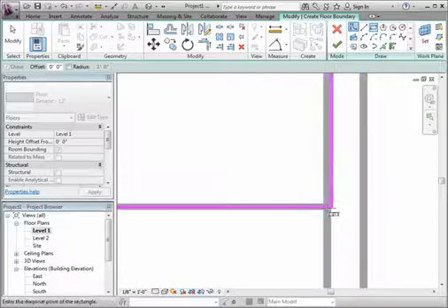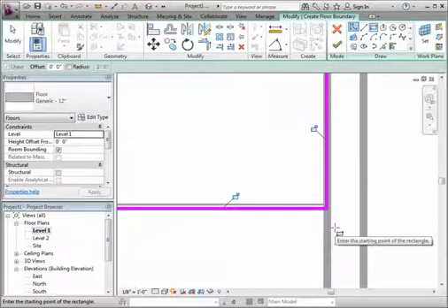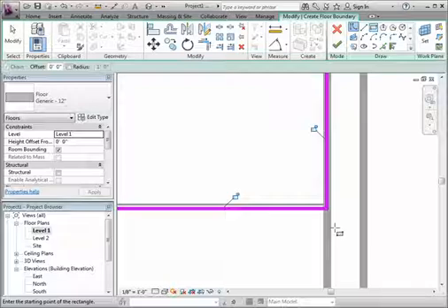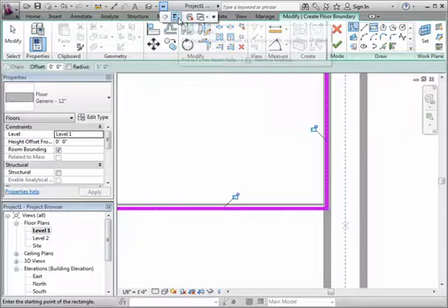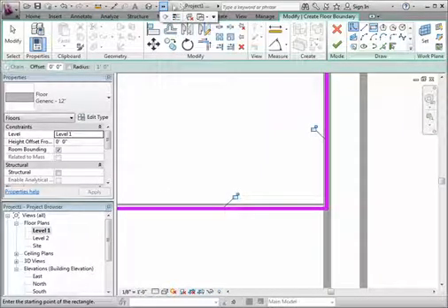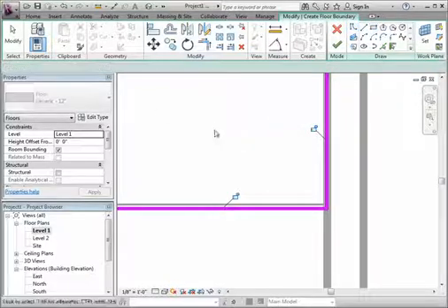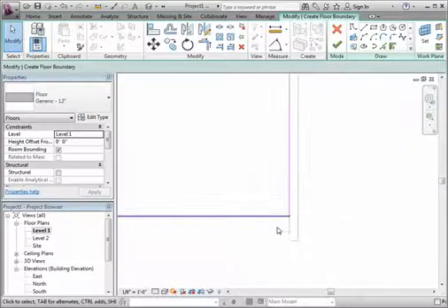This is what we'll do. And you might notice right now that it's hard to see exactly where I'm gonna finish because the line work is so heavy. One quick key or one little tool up here, which seems to be missing, is this right here. It's called thin lines. The quick key is TL. So if I type TL, you'll see that the line work goes to extremely thin, so I can see a lot better.